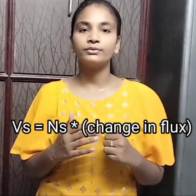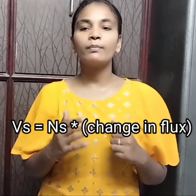When the secondary coil comes in contact with the primary coil's magnetic field lines, some EMF is induced in the secondary coil. And by the above lines, we can state a formula that Vs is equal to Ns into dΦ by dt, where Vs is secondary winding voltage, Ns is secondary winding turns, and Φ refers to the flux produced in the primary coil.